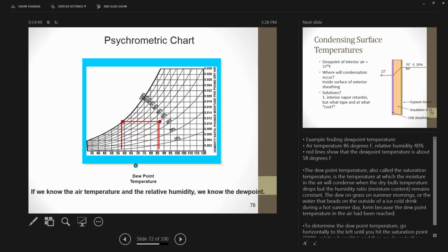It's a better way to measure problems with potential building assemblies, but it's still not an absolute, because it doesn't take into consideration the storage of the materials. It's just a point in time measurement, telling you where the moisture vapor has the potential to become bulk moisture. So it still doesn't necessarily tell you that you're going to have a problem with your wall assembly.